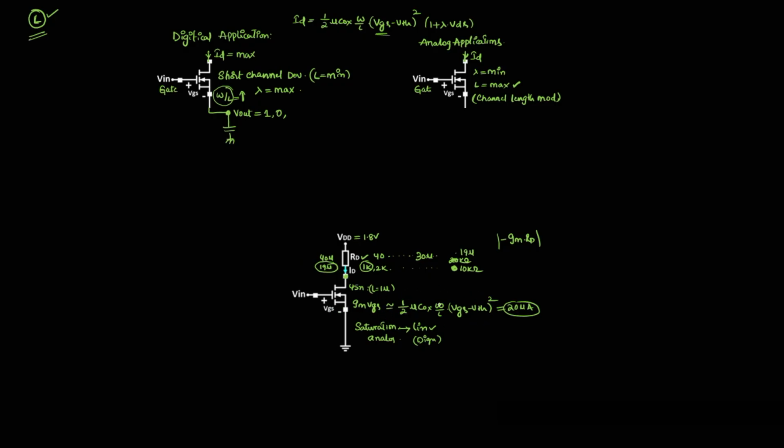As we know, if the W value is reduced, the transistor may expect less than the previous value, so that the transistor may come into the saturation again, right? So here we can make some modifications across the transistor. We can do proper sizing by adjusting the W value so that we can expect less current, so the transistor may be brought into the saturation, right?